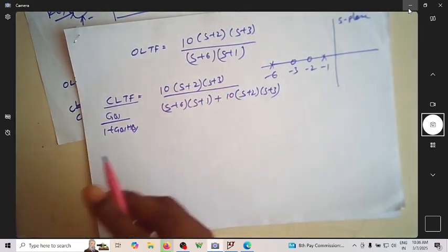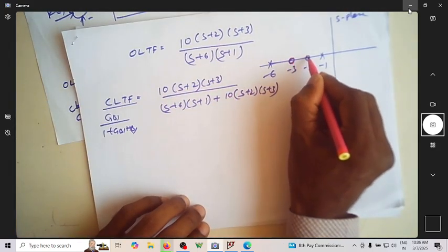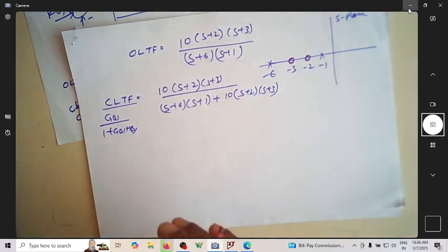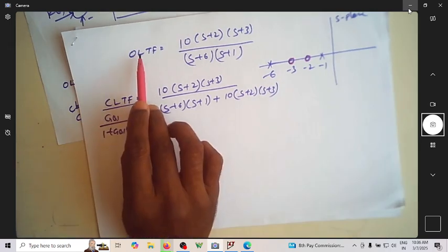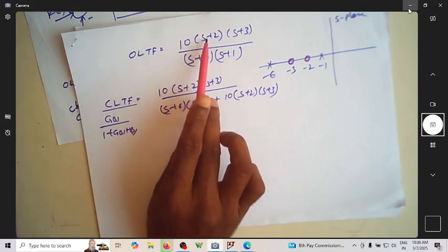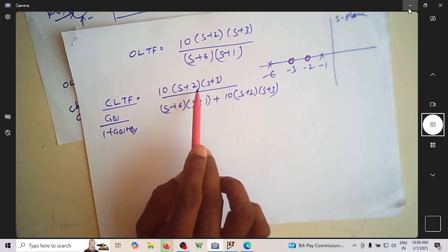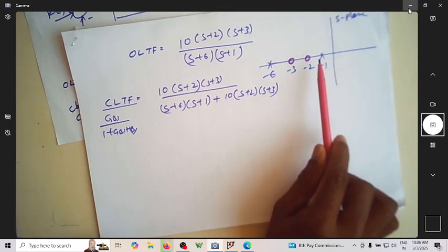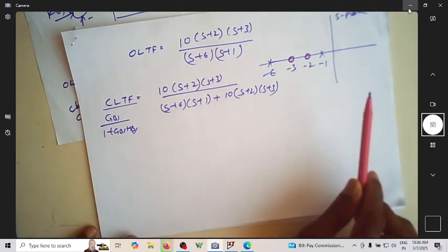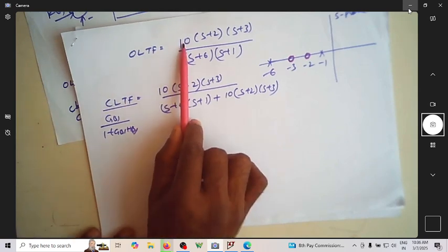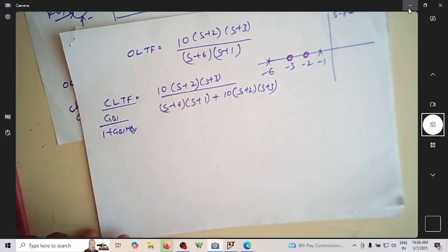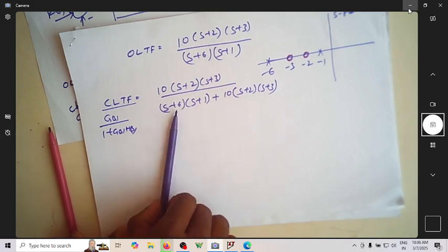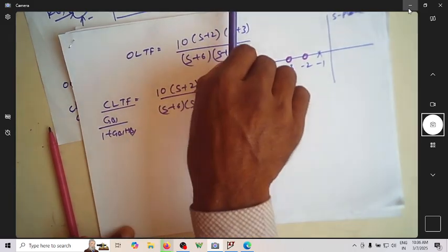You can see zeros will be there at the same point, whether you open the loop or close the loop. So this is what we are supposed to take out from open loop to closed loop. The difference of zero position from open loop and closed loop is absolutely same. So there is no movement, but poles will certainly move depending on what is this value and what is this value. So let us see what is the pole position when you add a 0 to this.